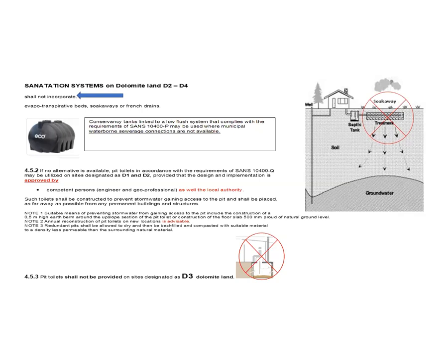Conservancy tanks need to be used where there are no municipal waterborne sewage connections available. So that when the sewage goes into it, it needs to be collected by one of those suck-up truckies, and they take it away to a place where they can dispose of it in a proper manner. But guys, if an alternative is available, I just want to touch on pit toilets.